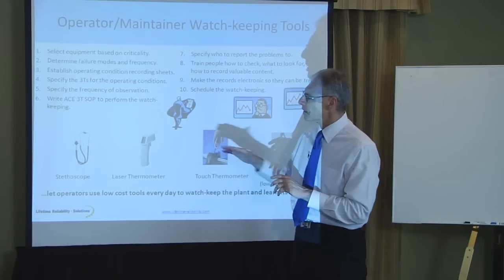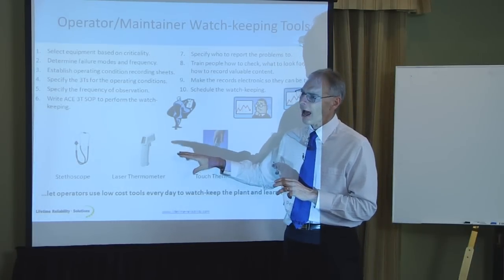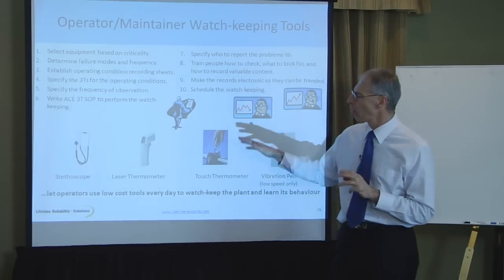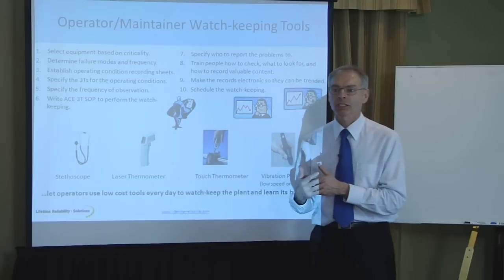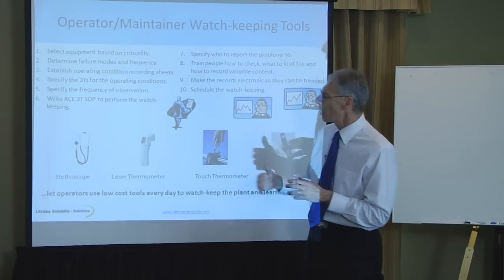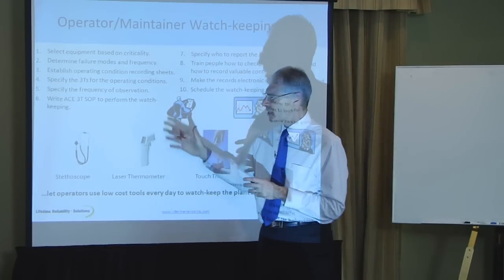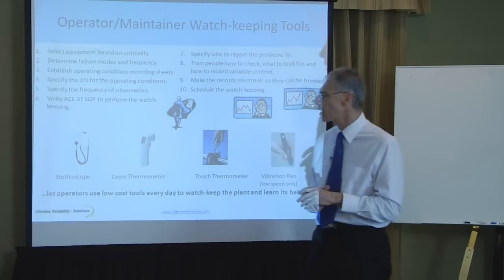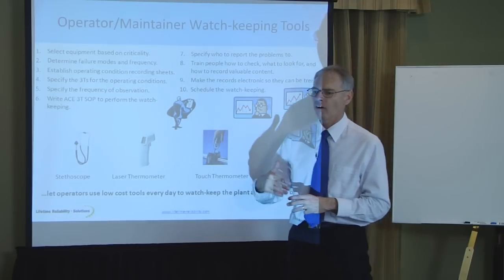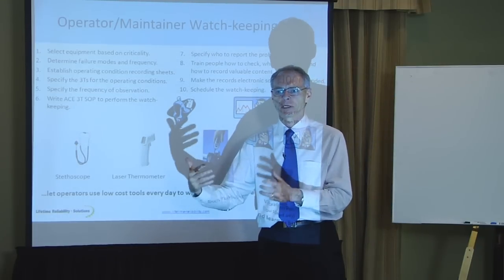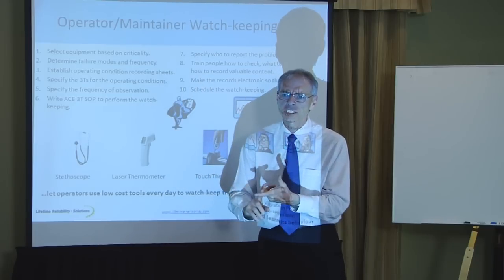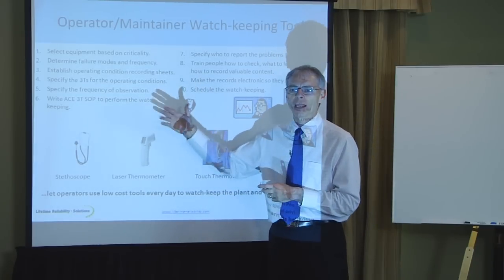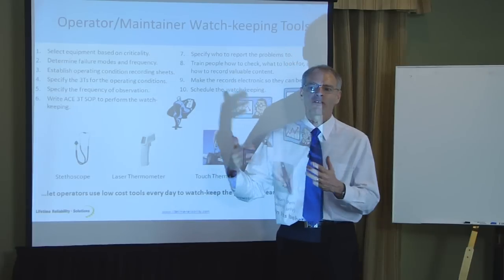I should also say this is a manually driven process. As technology develops, a lot of this stuff can be mounted on the machine itself. You actually mount the sensors. When it comes to noise and vibration and temperature, there are sensors out there we can actually mount on our machines. And a lot of companies are having the option, when buying a machine, of asking them to option in the sensors for vibration, for temperature, and feed those outputs back to our computer and monitor it 24/7 all the time.